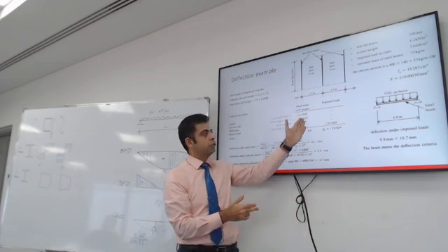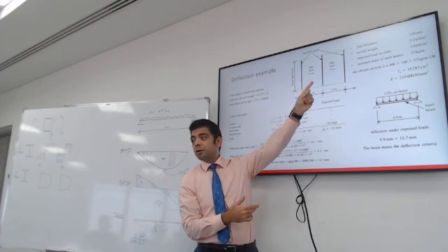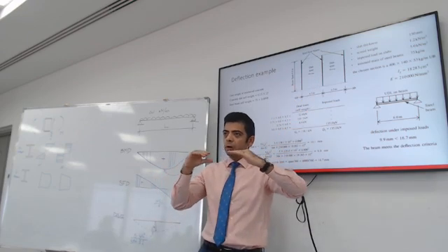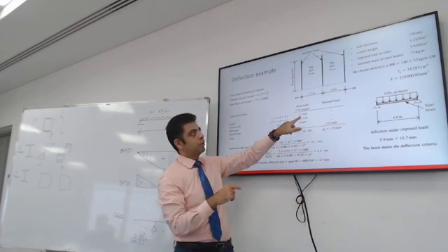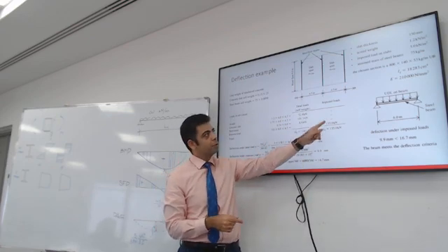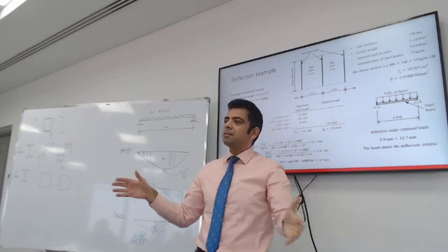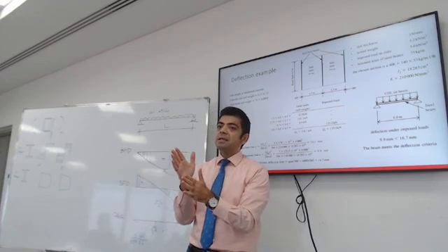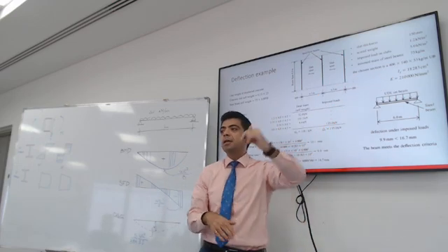So after you do the analysis, you will realize that the thickness of the slab is dead load. Any finishes or screed or topping, whatever is permanently on top of the slab, is dead load. The self weight of the beam is dead load. The only live load is the live load. So there is just the weight of the occupants. If this was an office space or whatever the use is, you go to the code, see according to the use of the space, what is the live load. It happened to be 5 kilonewton per meter.